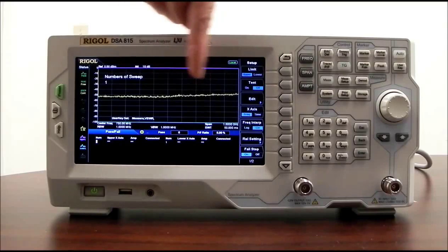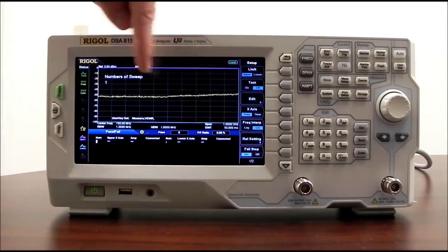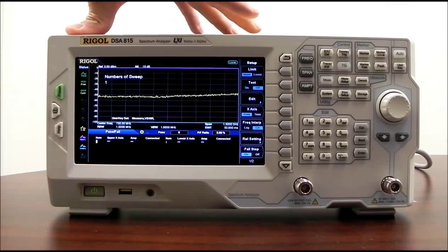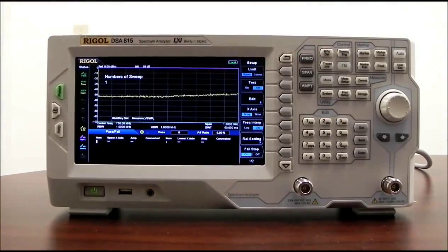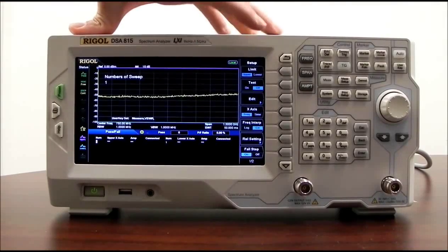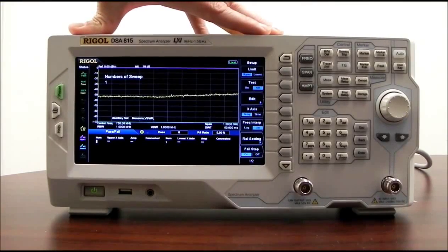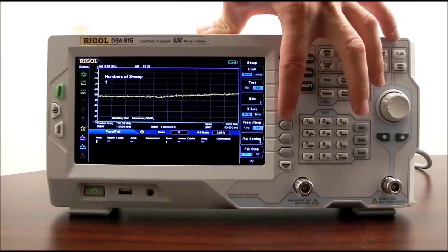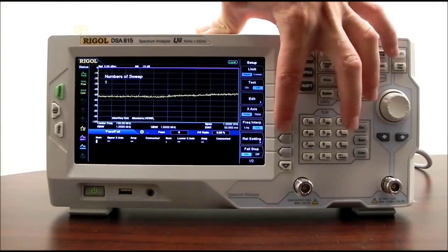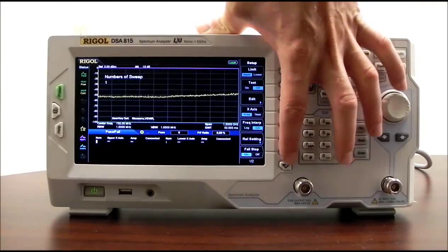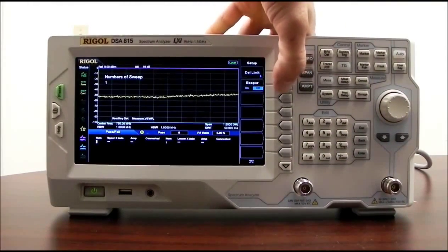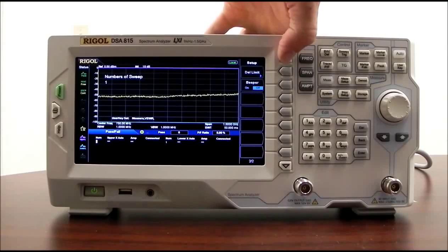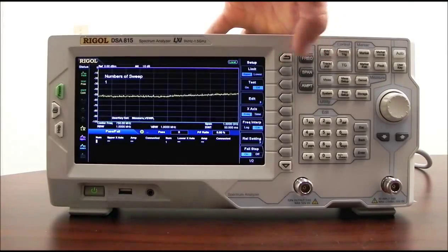Let's say we were doing frequency modulation. We could build a window around the frequency modulation. If that frequency went outside of the upper limit, it would be a fail. Or we could also use the limit line, upper limit lines especially, for EMI and EMC compliance. We can have a dB value that cannot be exceeded at a particular frequency range, and if we were to pass over that value, we would have a failure. We could set the x-axis as frequency or time. We can do frequency interpolation, log or linear. We can do relative, and pass or fail we can stop on. Let's go to page 2, and we can delete our limits, and we could also turn a beeper on if we wanted to have an automated test. So that can be very helpful in an automated test environment.